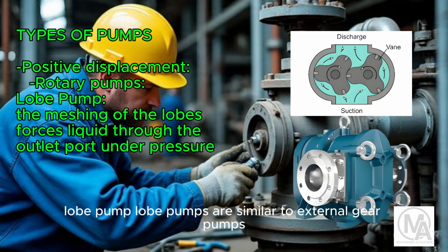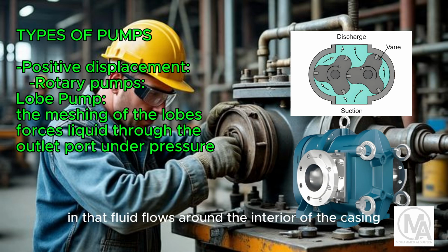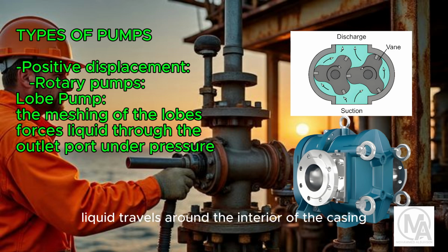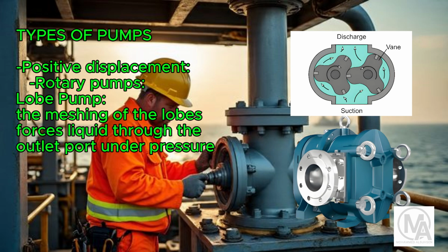Lobe pump. Lobe pumps are similar to external gear pumps in operation, in that fluid flows around the interior of the casing. As the lobes come out of mesh, they create expanding volume on the inlet side of the pump. Liquid flows into the cavity and is trapped by the lobes as they rotate. Liquid travels around the interior of the casing in the pockets between the lobes and the casing. Finally, the meshing of the lobes forces liquid through the outlet port under pressure.